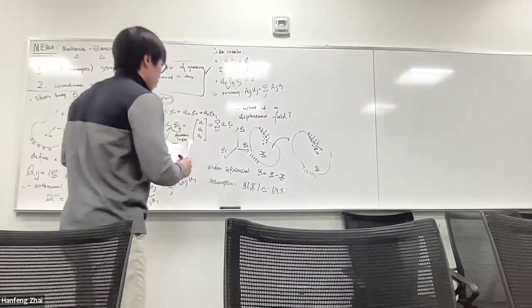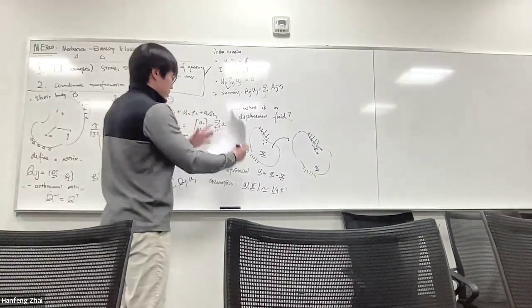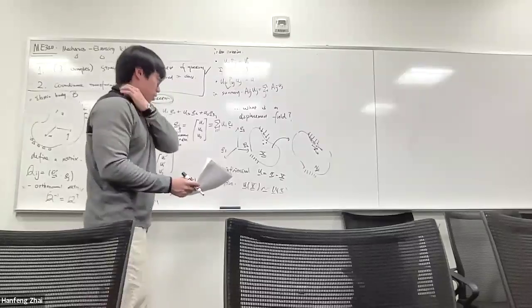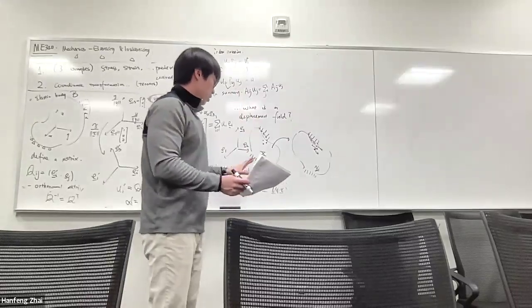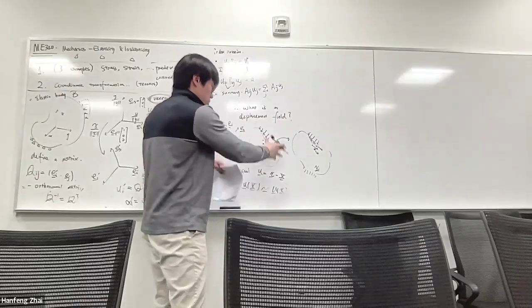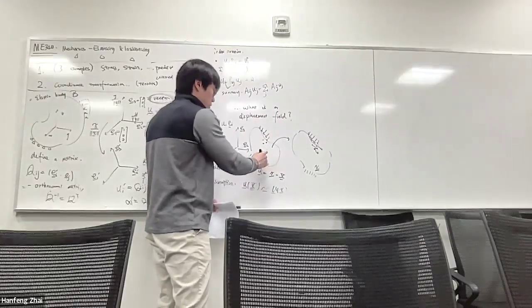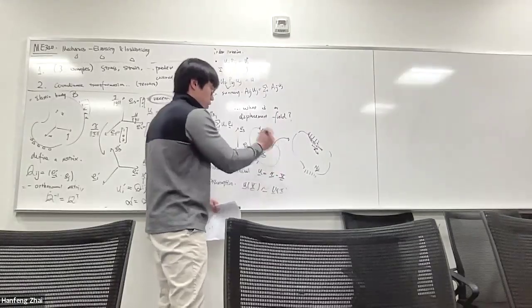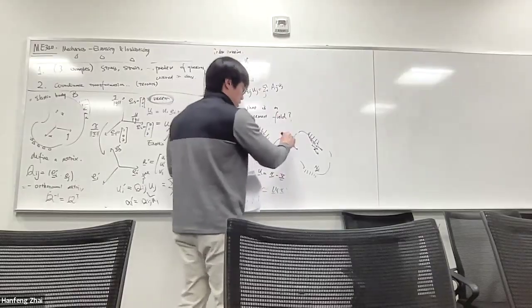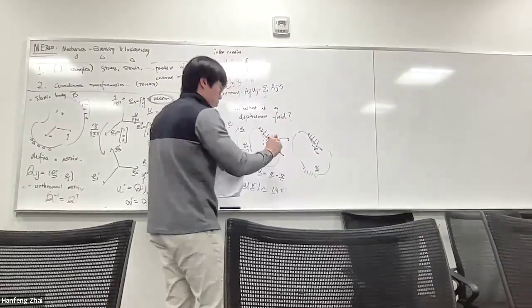I'll revise the part. Okay, so what is the displacement field? We establish a coordinate system, and the coordinate system is not changing. We are not transforming the coordinate system. Under this material body, we first define this configuration where we represent all the points in vector form as capitalized X, which we call the reference configuration, and then we deform the body. Now we can track the different material points.